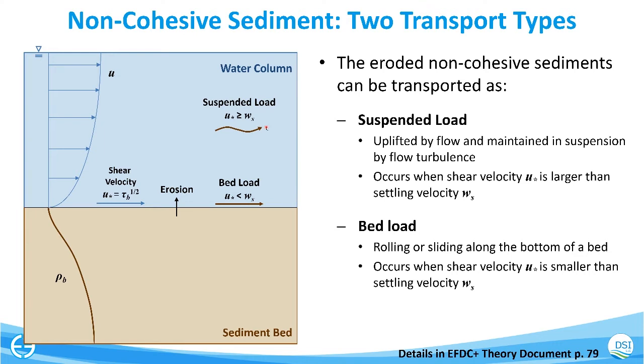So the suspended load means the particles are uplifted by flow and maintained in suspension while they are traveling by flow turbulence. And the bed load means the rolling or sliding along the bottom of the bed.